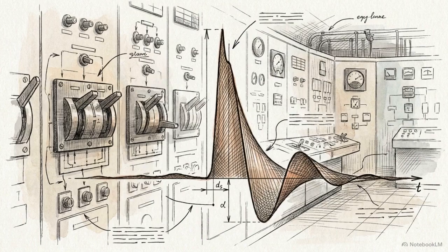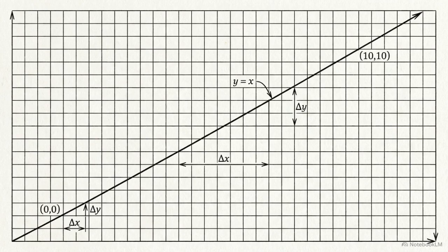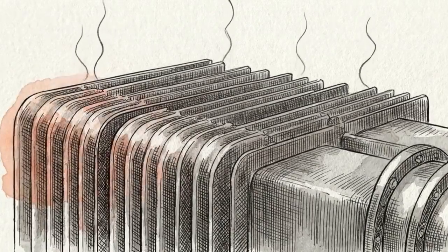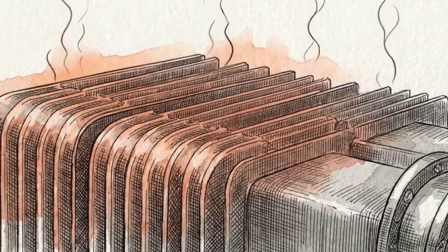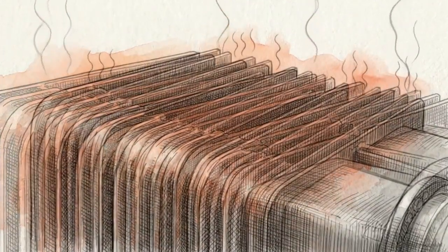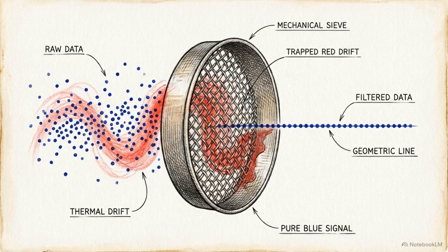The engineering recommendation is clear. Automated diagnostic systems should monitor the peak amplitude of the step response at its first extremum to track axial displacement online. Naturally, this mathematical proof operates within the strict boundaries of system linearity. Real-world deployment must account for external variables not modeled in this baseline simulation, most notably the baseline shifts caused by operating temperature fluctuations inside the transformer. Filtering out that thermal drift is the next hurdle in refining these algorithms. But the core logic holds.